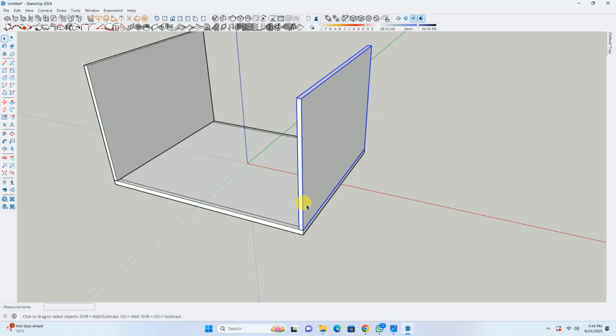Okay. So we'll select the object. We'll press Q, and first of all we'll specify the axis about which we want to rotate our object. We want to rotate about the z axis, so we'll hit the up arrow key so that our plane is locked.